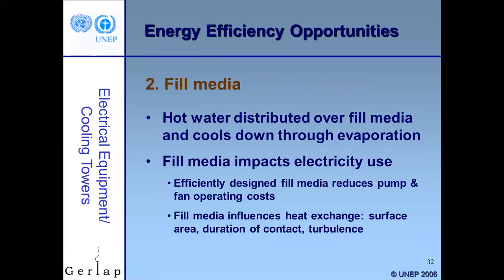Okay, that's pretty good. What type of fill media? Like we said, the film fill is a little more efficient than the splash fill. I would suspect that these days that's what you would probably be looking at. But we know the hot water is distributed over the fill media, cools down through evaporation. Fill media impacts electrical use. If it's more efficient, then we don't need to run the fans as much. We can get away with less water being moved, etc.